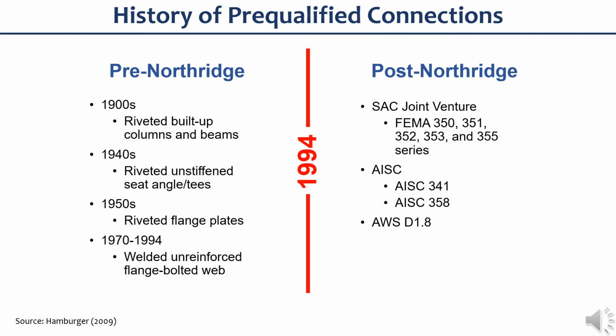Now, after that discovery, the SAC joint venture conducted extensive research and published a series of reports known as the FEMA 350 to 355 series. And following the SAC results, the concept of pre-qualified moment connections was subsequently incorporated into the AISC seismic provisions in 2002.